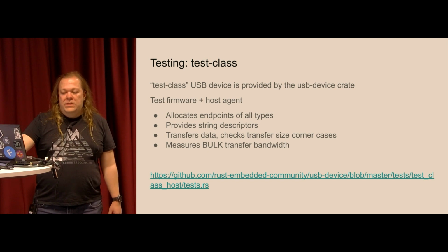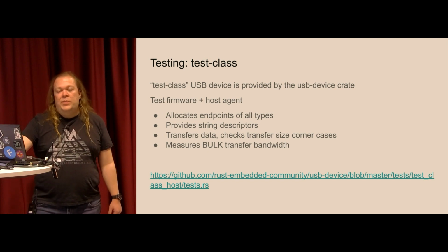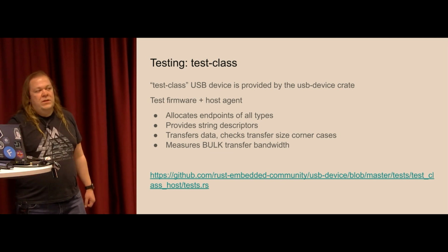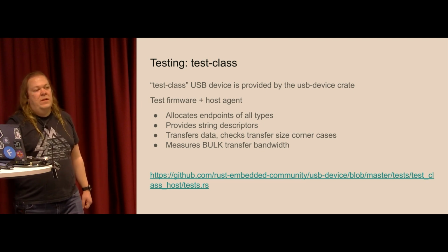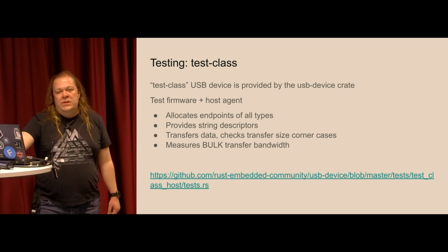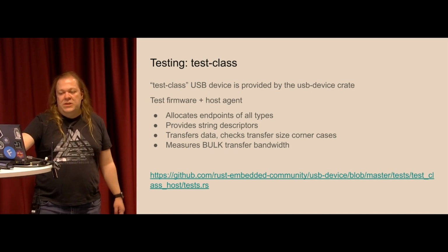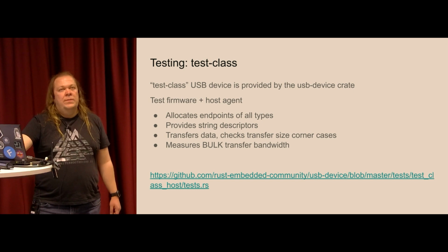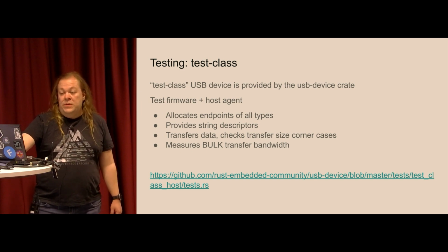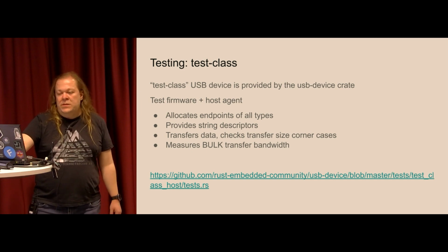So, as I said, we allocate endpoints of all the different types to verify that they are successfully allocated, and that the parameters of these endpoints are the same as they are supposed to be in the device implementation. There are also string descriptors, which are tested not only for different interfaces, but also, I think, for different languages, because USB supports these, so why not test it?